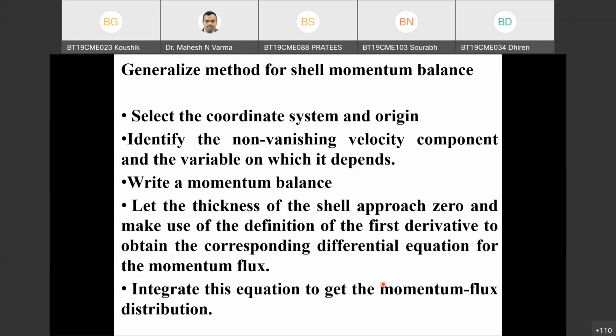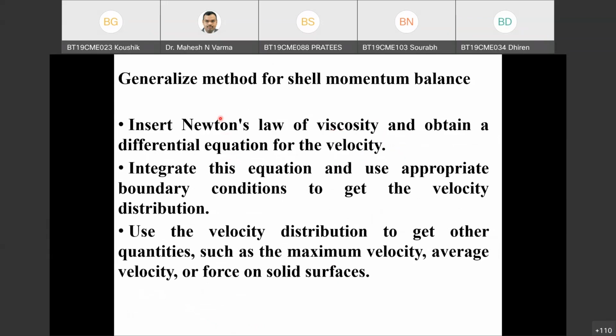You only need to extrapolate the information appropriately, given the similarity between all these three variables. Here I am discussing velocity. In heat transfer I will be discussing temperature. So I cannot discuss velocity and temperature in x, y, z directions. You should remember that temperature is a scalar, velocity is a vector, and concentration is used in mass transfer. Similarly, instead of Newton's law of viscosity you will use Fourier's law of heat conduction, and in mass transfer, Fick's law of diffusion.